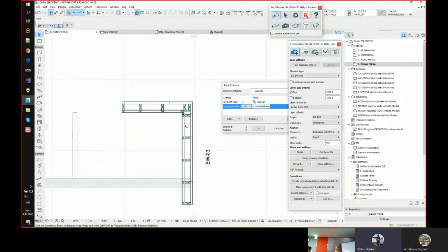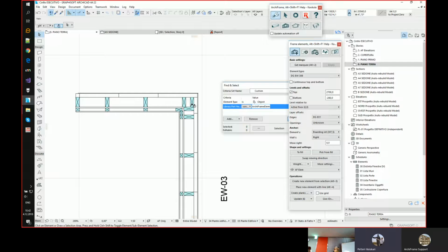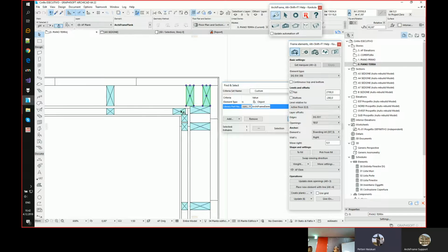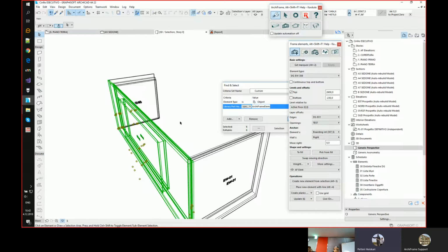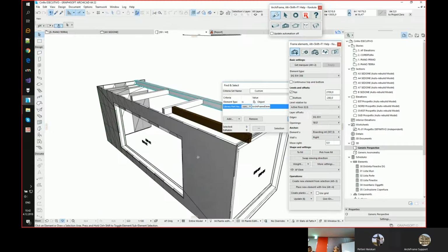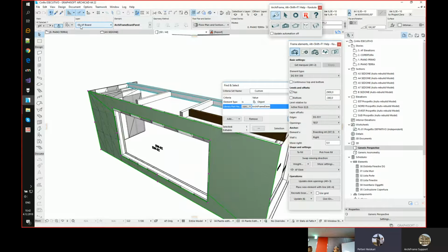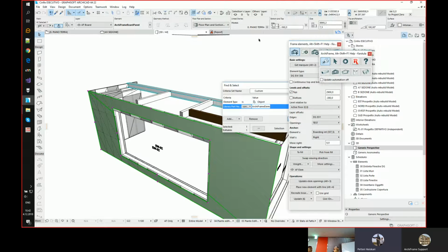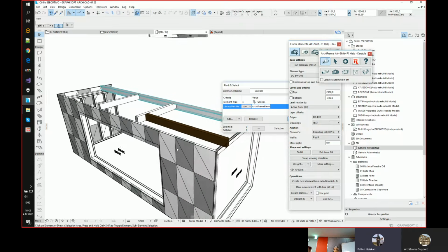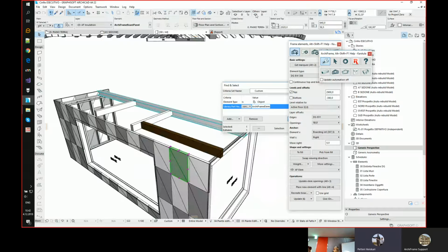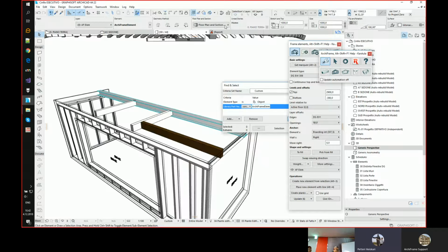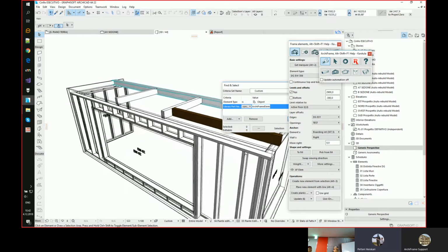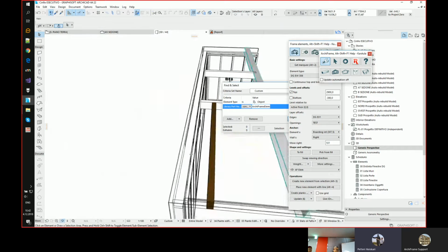And this is the result in floor plan. So these are from the corner rule long, and this is also, it comes from the corner rule. And the same result we have a look in 3D. I can hide these layers, so we have this in the board layer. I'll use ArchiCAD's quick layers to hide these boards. Then we have insulation, it is in its own layer. I'll hide that also so we can see the main framing and also framing at the inner side.